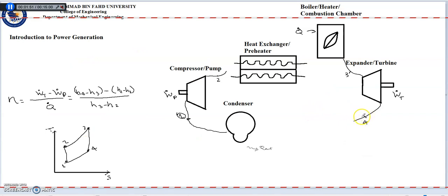So take the fluid from 4, connect it to our heat exchanger, then pass the fluid in the condenser, and on the other side of the heat exchanger, preheat our incoming fluid from the exit of the pump.